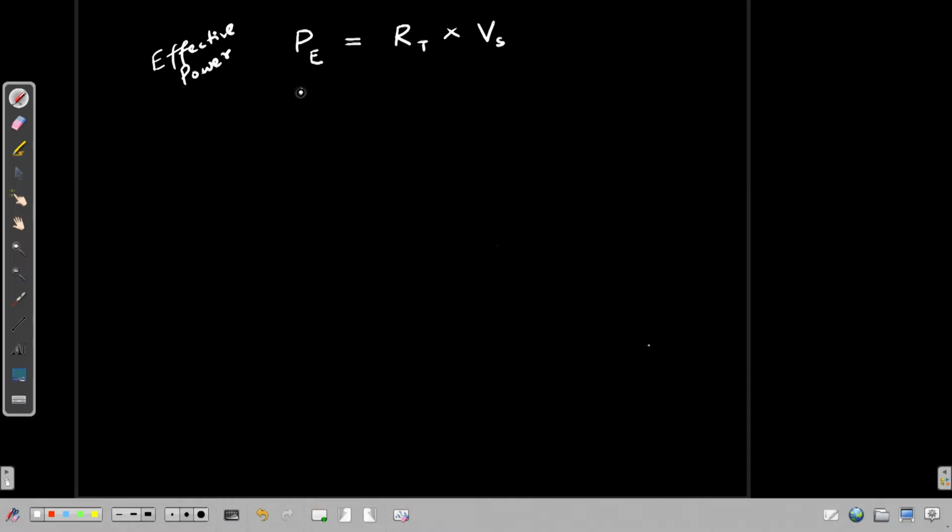Next, we have the delivered power, which is the rotational speed into the torque for the propeller. We say QB, which is the torque in the behind condition, or we can write it as Q only.